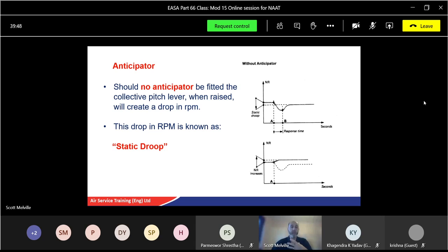It's just like a propeller aircraft. We've got the bending force going forward, so it slows the engine down. A rotor on a helicopter is the same thing, except instead of being at the front of the nose, we've got it going up. The angle of attack is increasing. It's trying to pull the helicopter up, but it's putting more stress on the engine because with a greater angle of attack there's more air it's trying to push around. So it's going to slow the engine down, which overall, yes, we get lift in the blades, but we don't get lift on the helicopter. So we need to increase power.